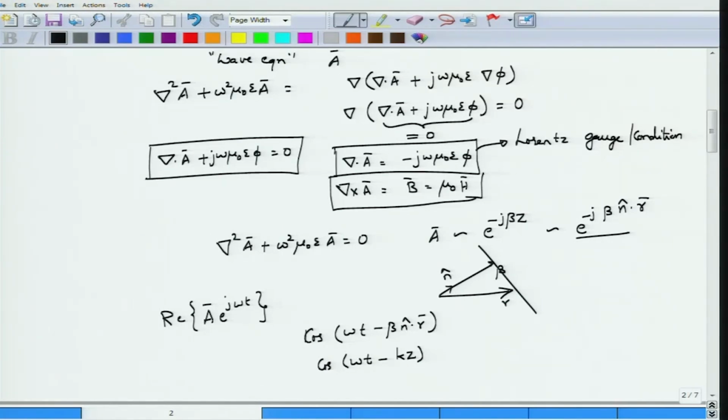So what we have in fact shown is that this is a wave equation and A will wave along a particular direction beta, and there is a corresponding propagation constant beta that we can define. Because of this wave nature, we also know that if there is a disturbance at t equal to 0, if A changes suddenly from one value to another value at t equal to 0, then this disturbance won't be visible to me if I am sitting at a distance of L from the source.